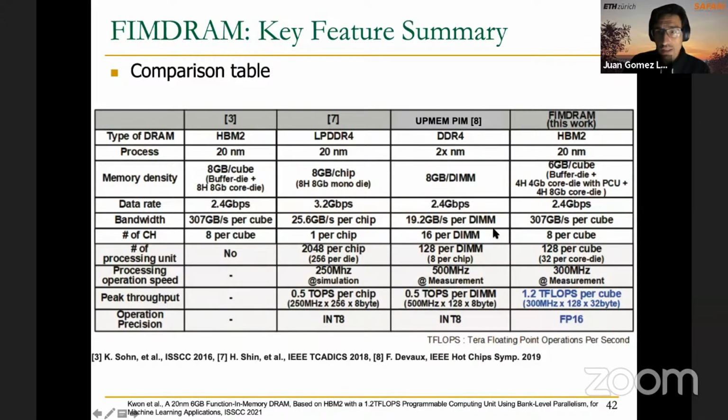HBM2, this is for a single DIMM, but you can also think about what would be the total bandwidth that you can achieve when you have, in a PIM system, more than one DIMM. You can have up to 20 DIMMs. Remember, 40 ranks in the larger system that provides these days, and probably you are not going to have so many cubes of HBM, especially because one reason is the additional cost that this memory has.